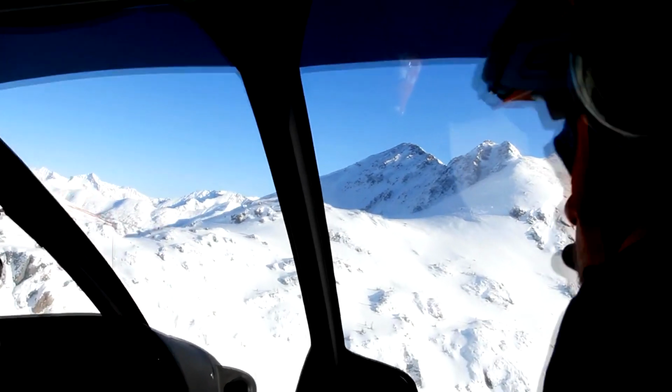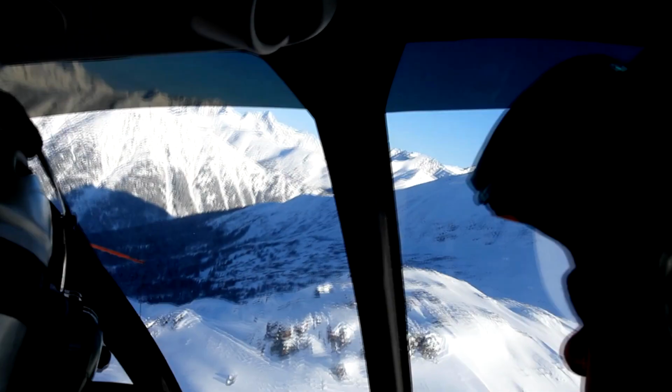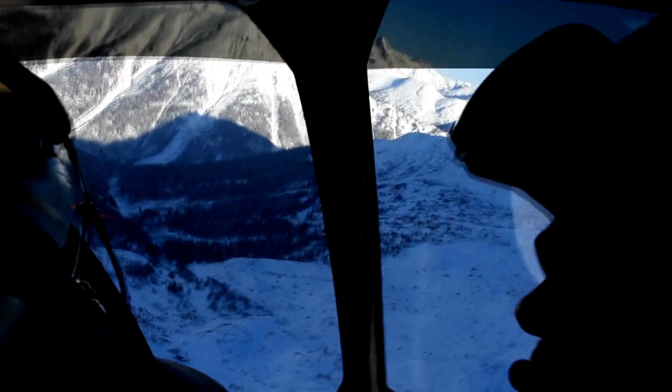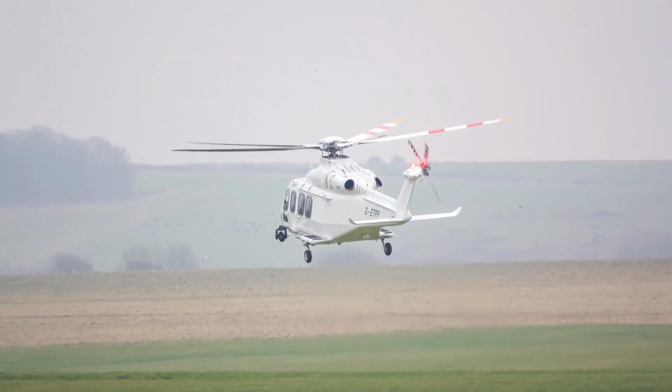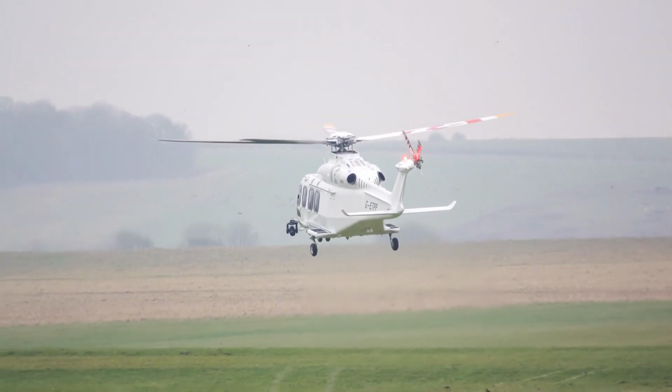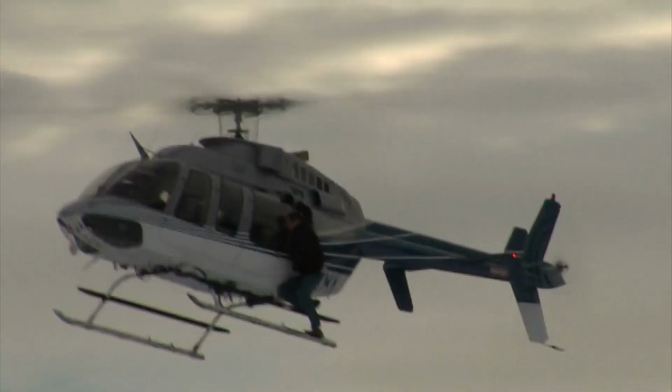As the helicopter gracefully maneuvers backward, envision two reference points selected in front and in line with the aircraft, serving as visual guides throughout the intricate performance. The helicopter begins its gentle rearward movement from a standard hovering height, with the pilot applying subtle rearward pressure on the cyclic. To maintain precision, the cyclic is deftly positioned to ensure a controlled and deliberate ground speed, no faster than a brisk walk.